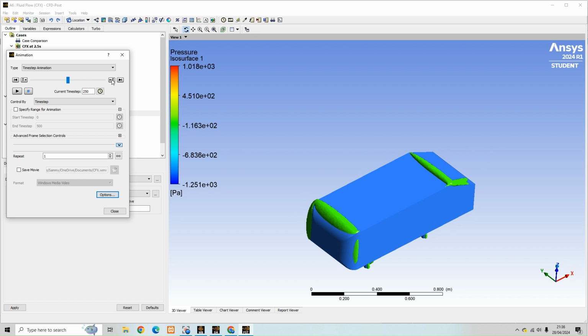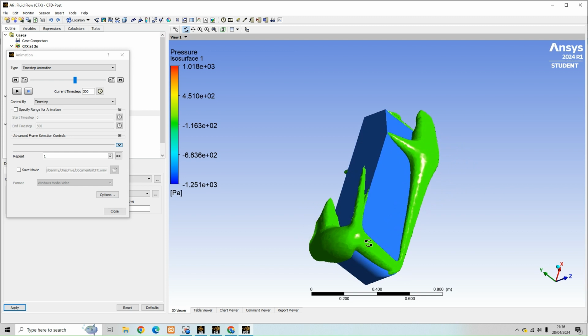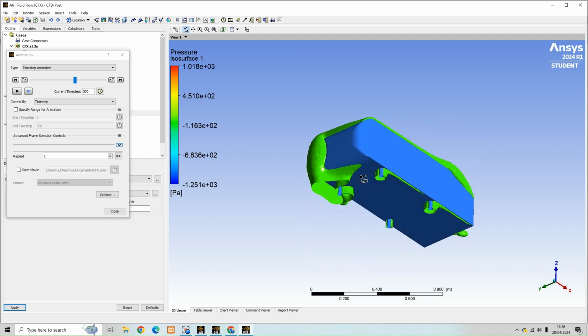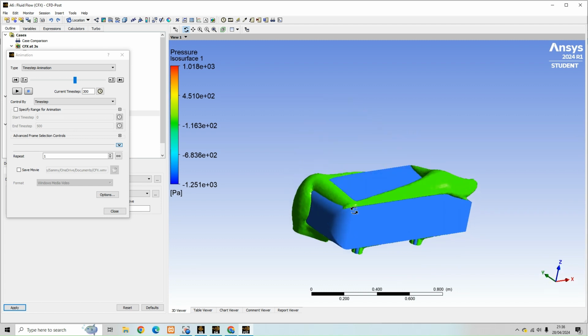Okay, that must be one of the parts where the airspeed died down a bit. Yeah, got this kind of classic leading edge separation vortex that you get from side winds and then kind of around the leeward face. That's kind of exhibited a bit in the struts as well.